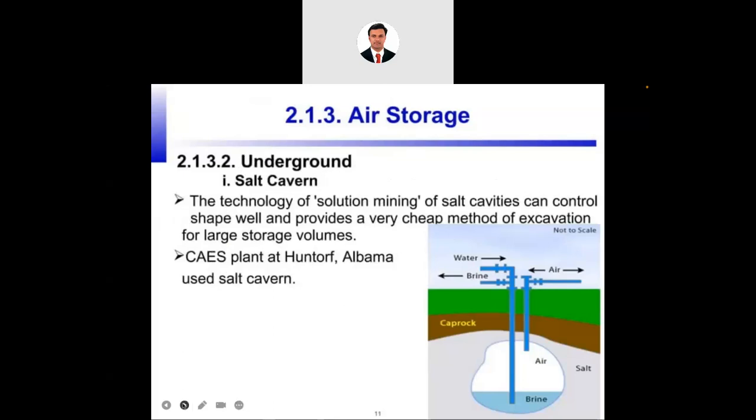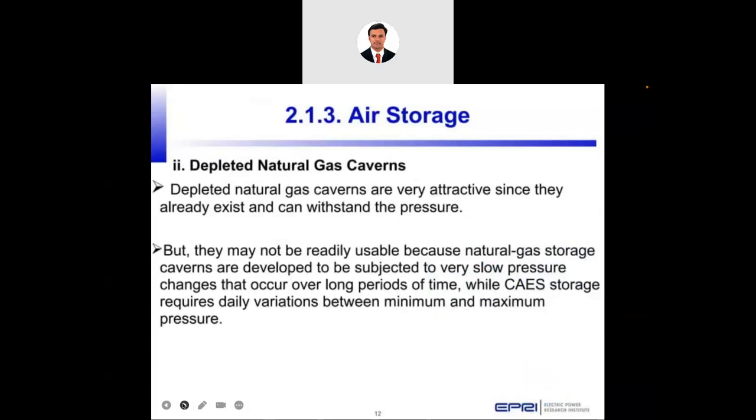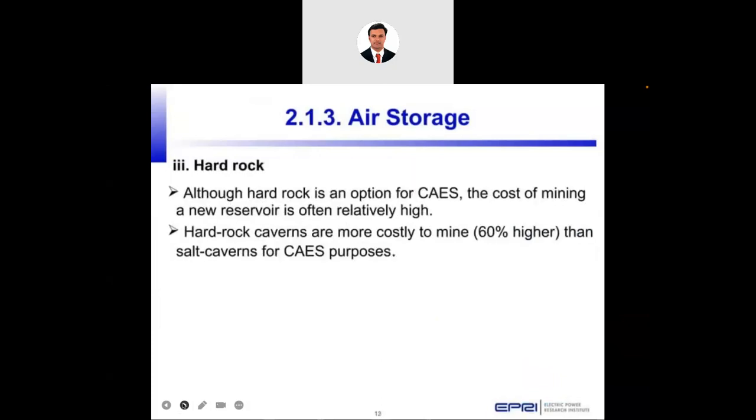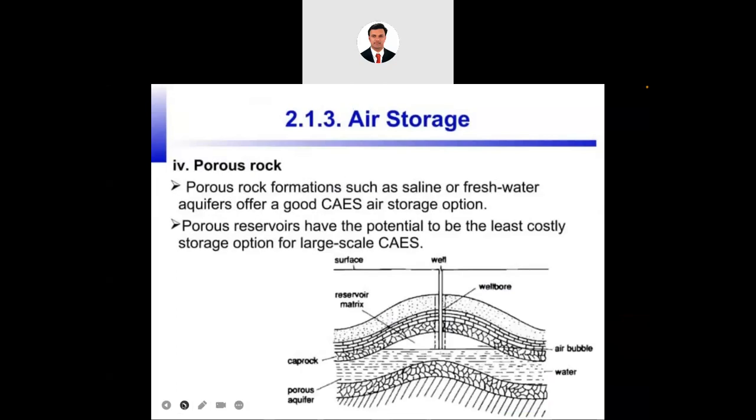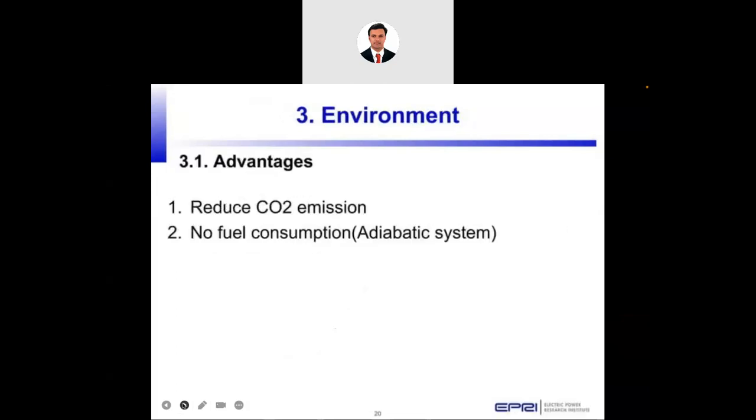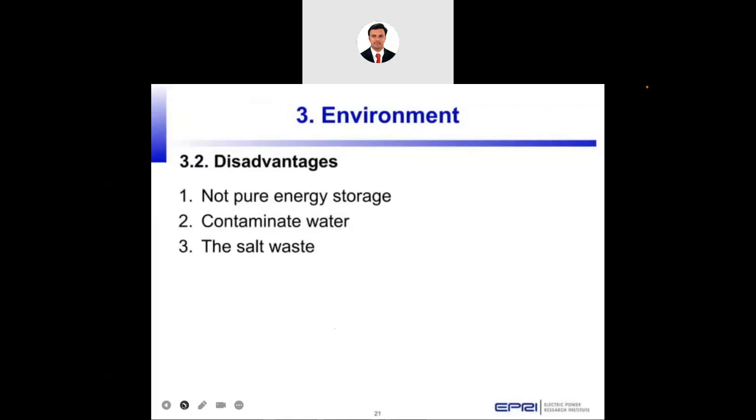To reduce the cost, we generally use underground storage facilities. In that case, you can use salt caverns, depleted natural gas caverns, or hard rock caverns. This air storage has very high capacity values. It has some advantages: it reduces CO2 emissions and doesn't require any fuel consumption. So these are the advantages.